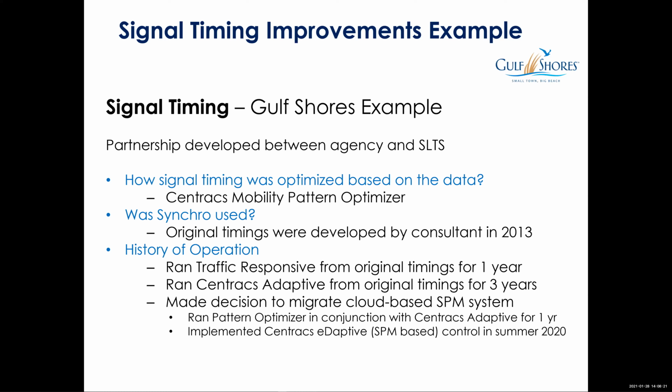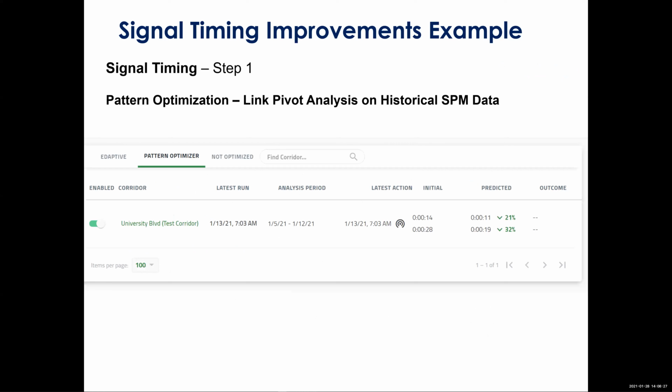The thing is, adaptives work really well, and the way they're supposed to handle traffic is to be able to maintain traffic over time, so that you don't have to go out and do as many timing studies. The adaptive control should maintain a good coordinated arterial and keep it running for several years, just by making the adjustments on a minute by minute basis.